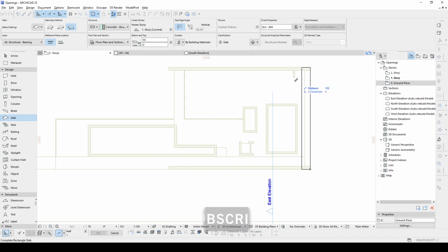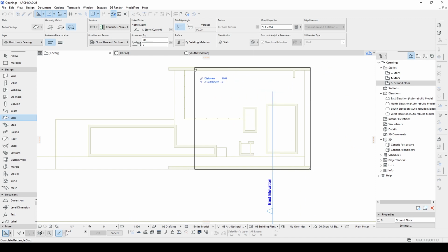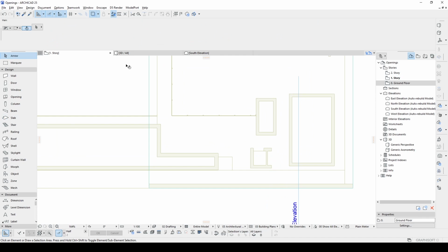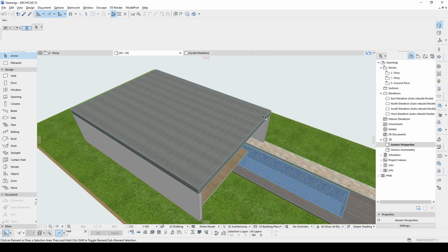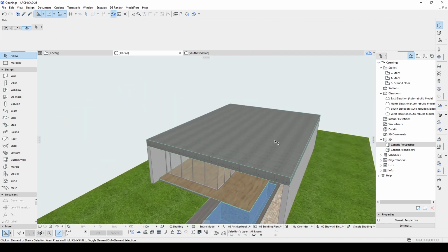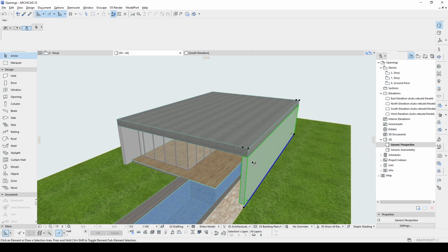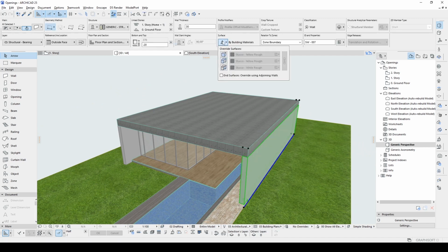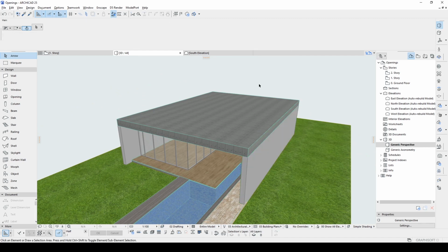First, we are going to create the first line, and second, the direction line. We can do this because we have selected the rotated rectangular. There we go. We have created the basic part of the roof, and now I prefer changing the material. For that, I'm going to make that concrete.